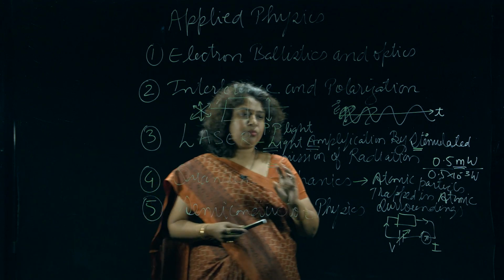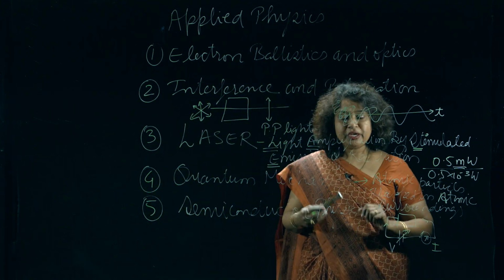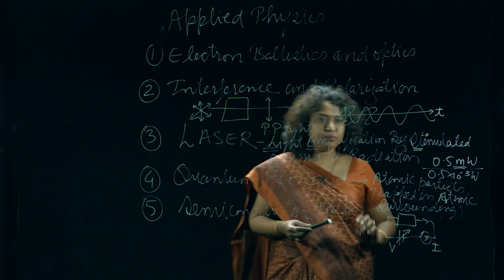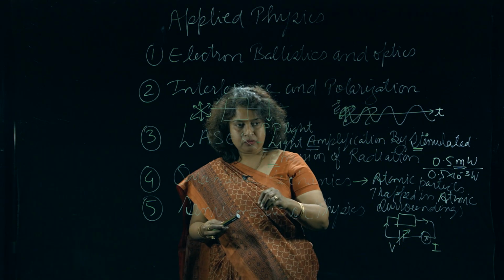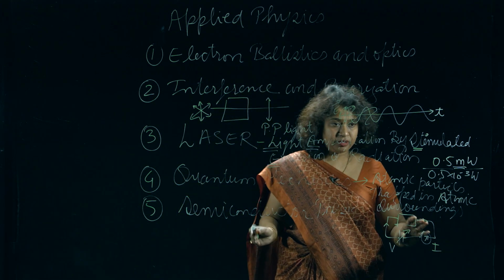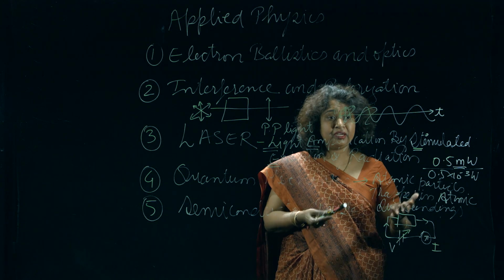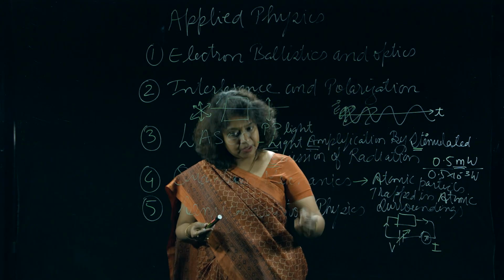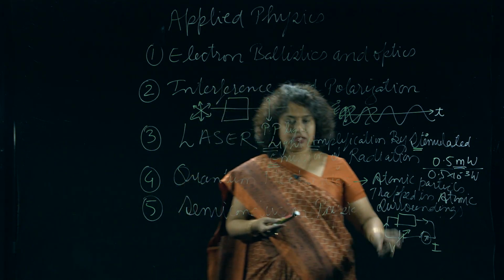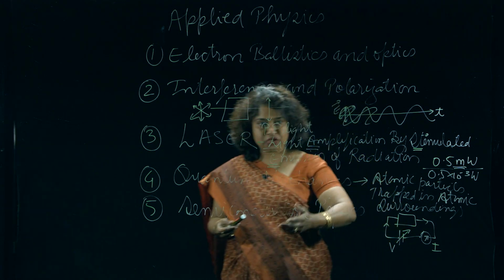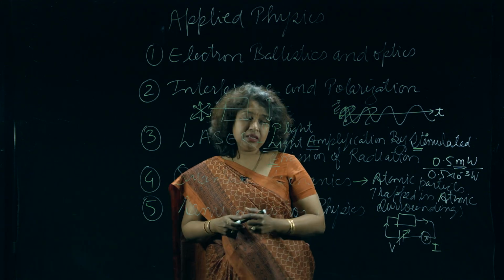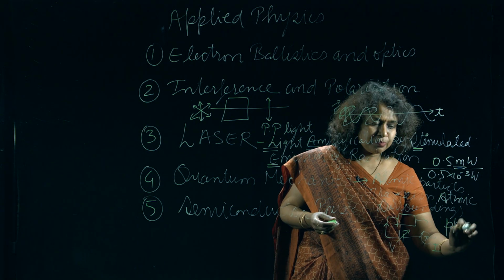Now, this is a very, very important material, because you can manipulate their conductivities, right. This class of materials is very important because of doping. What do you mean by doping? Addition of impurities, right. Do we add impurity? We never add impurity. We want a material to be pure, 99.99% pure. But in semiconductors, deliberately we add impurity. What is the motive behind it? To manipulate its conductivity. We can change the conductivity of the sample by making it impure, but that impurity which we add is in a very controlled amount. What we say is parts per million, ppm.